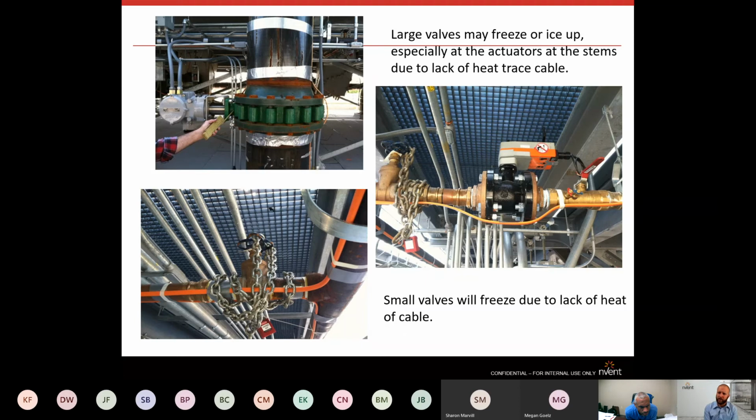And when you look at these photos, it may seem like it's not a big deal, but if you heat trace a whole bunch of pipe and then cover it up with insulation, and each circuit is a few hundred feet and it's tripping out, well, where is it? And I can tell you right now, there's no easy way to identify where exactly that issue is under the insulation. It's a hunt and peck game, and it becomes costly. And the other option is pulling off the entire heat trace run, which is expensive.